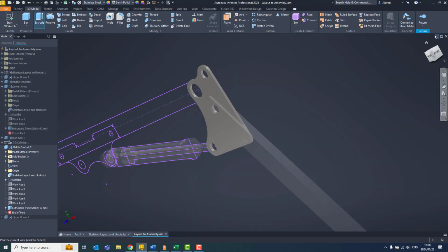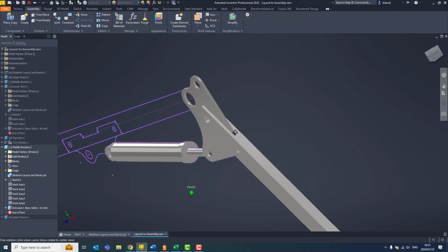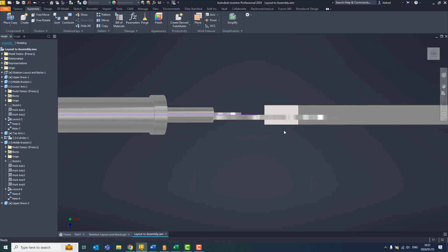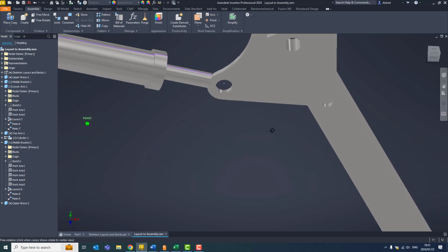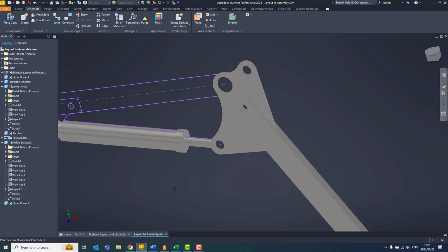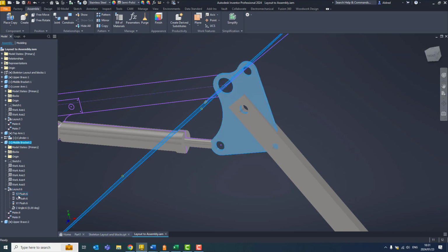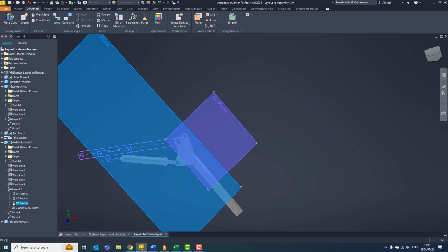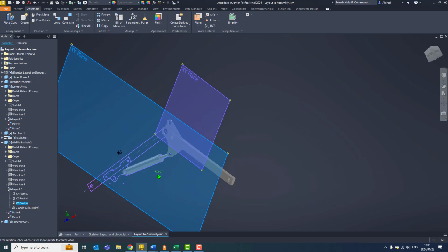Now the problem with this is that it's sitting inside or on that middle plane over there, and it's not wrong, because that's how we started off the layouts. It's all on one plane, and then we start designing it from there, and that's also what a 2D layout will look like. It doesn't show you the depth of where the sketch is actually sitting. So what we can do over here is just move it, and if I take a look at the layout at the bottom over here, we'll see there that it's been constrained as a flush constraint onto my XY plane.